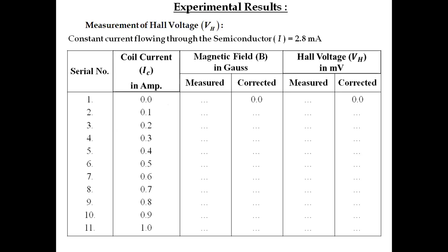But as I have shown you, you may observe some small amount of magnetic field in that gauss meter, and that may be due to residual magnetism. The electromagnet has been used before, so it may retain some residual magnetism, and you may observe that. But it is not correct ideally, because you are giving coil current 0.